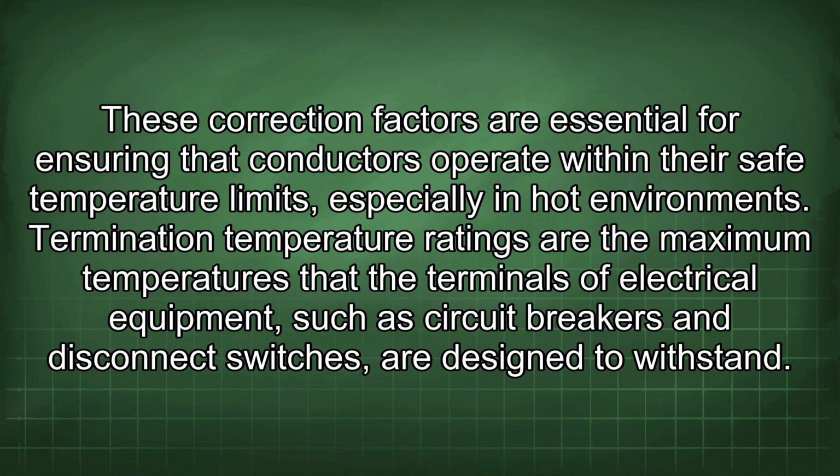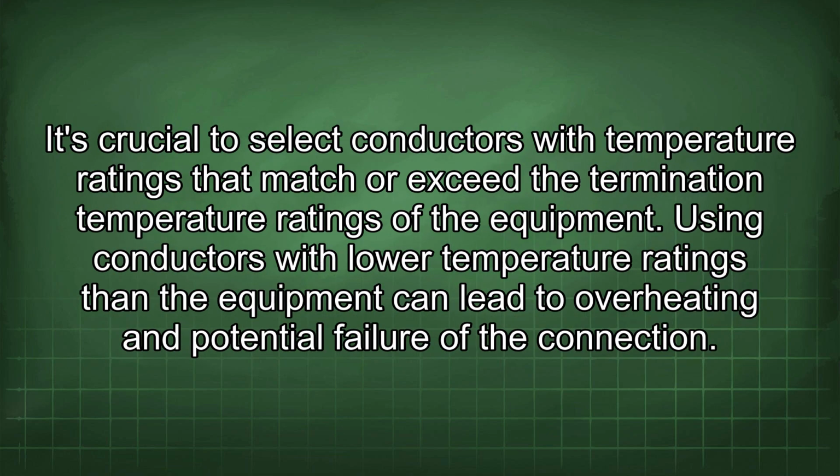Termination temperature ratings are the maximum temperatures that the terminals of electrical equipment, such as circuit breakers and disconnect switches, are designed to withstand. It's crucial to select conductors with temperature ratings that match or exceed the termination temperature ratings of the equipment. Using conductors with lower temperature ratings than the equipment can lead to overheating and potential failure of the connection.